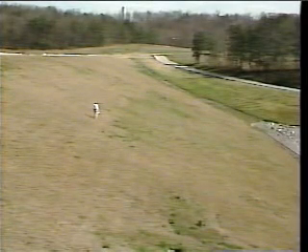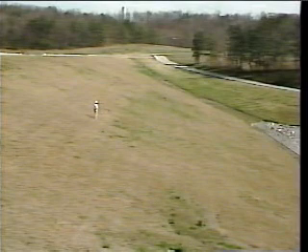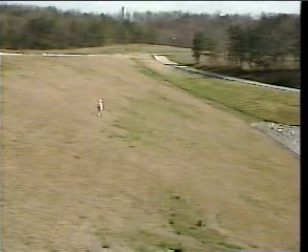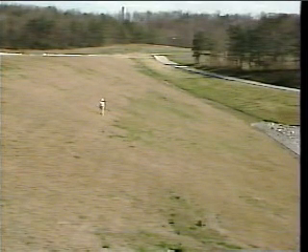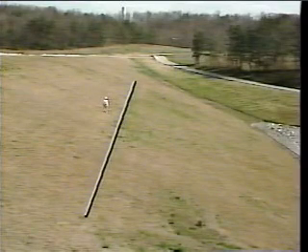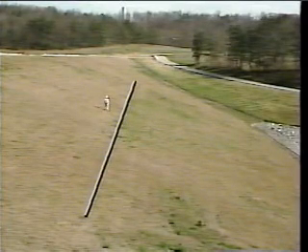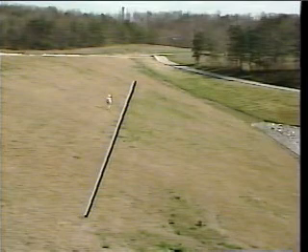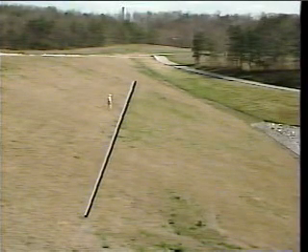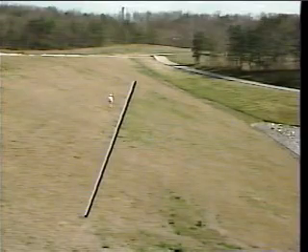Be on the lookout for vegetation on the downstream slope or below the downstream toe that's more lush or green than the surrounding area. Sometimes vegetation can form a horizontal line on the downstream slope. This probably indicates the intersection of the seepage surface with the downstream slope. This is a sure sign that water is at or near the surface.